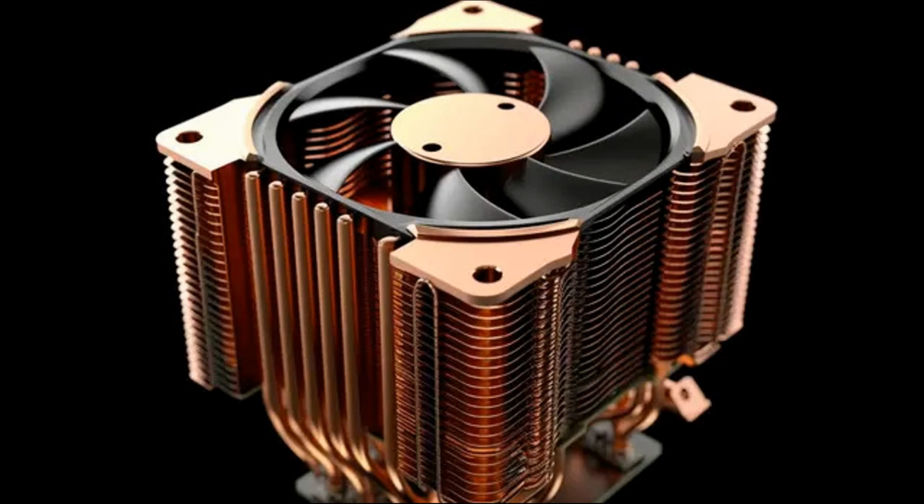Thermoelectric, Peltier, heat sink. Thermoelectric heat sinks utilize the Peltier effect to actively transfer heat away from electronic components. They consist of thermoelectric modules that create a temperature gradient when an electric current is applied, effectively moving heat from one side of the module to the other. Thermoelectric heat sinks are used in applications requiring precise temperature control or where traditional cooling methods are insufficient.